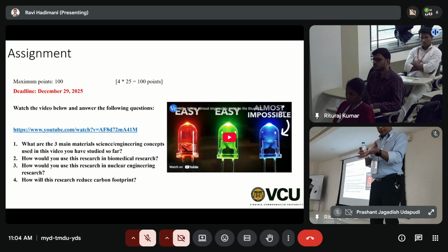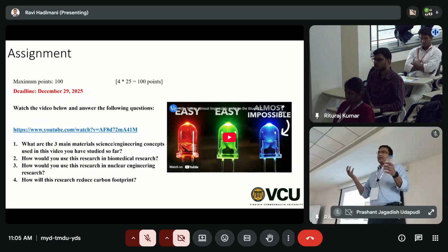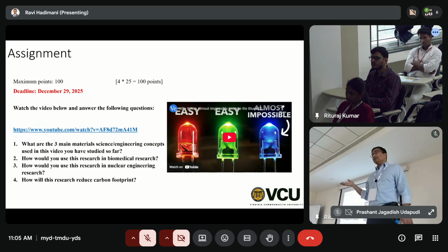It's the temperature, it's the conformity, it's the location of your, if you are doing a tool bit, a drill bit, it has to be mounted this way, right? And then for that, some physical vapor deposition methods will not work, right? Because they won't deposit on this side. So it's constrained by your application rather than whether it's PVD or CVD. And the other problem with CVD is you have to have metallic gas.